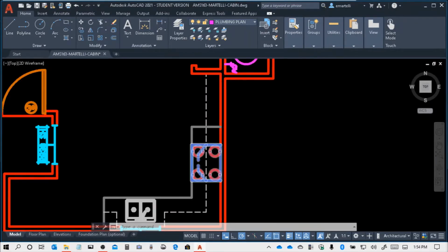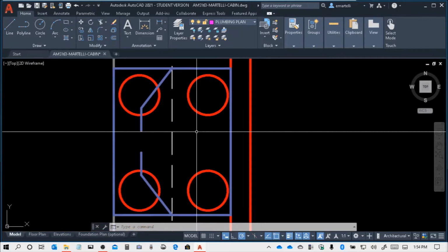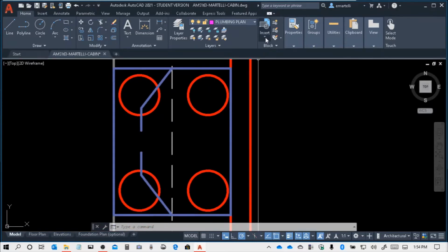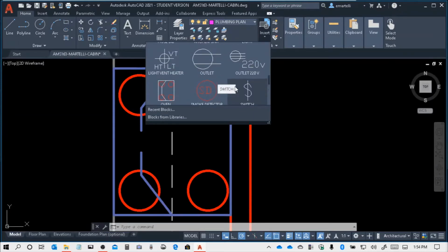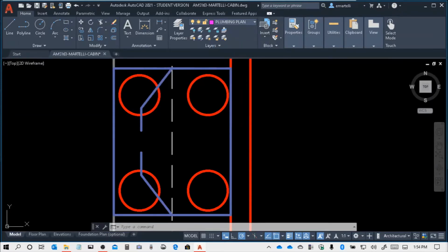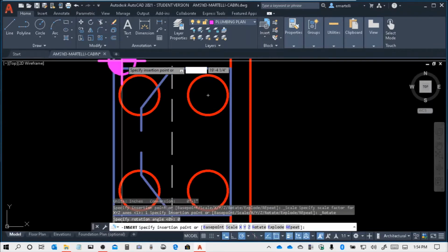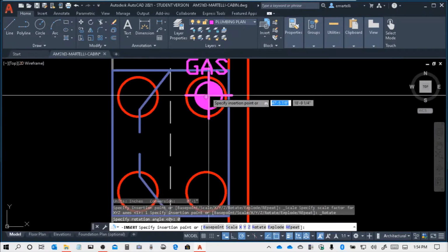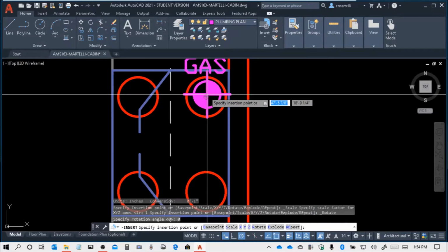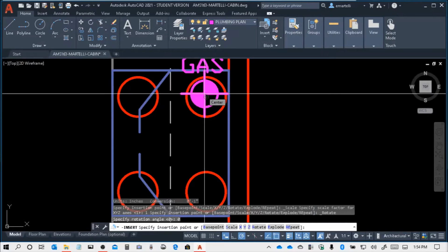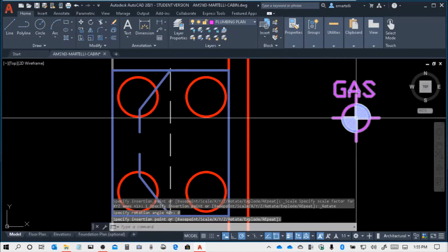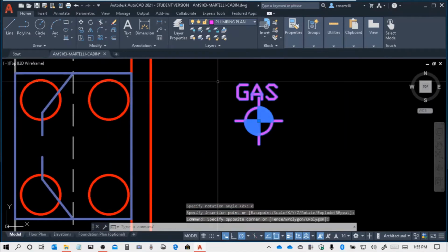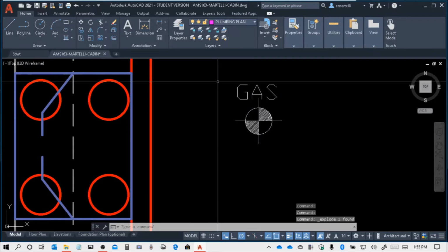Now, as I previously mentioned, this oven gets a gas symbol. So let me go insert, where was it again? Gas, right here. And you're just going to want to put that somewhere. Looks like they put it about here, but they changed the way it's going to look. So what I'm going to do is put it here. Then I'm going to select it, explode. Beneath erase, above offset, explode. It's going to bring it back to the zero layer.